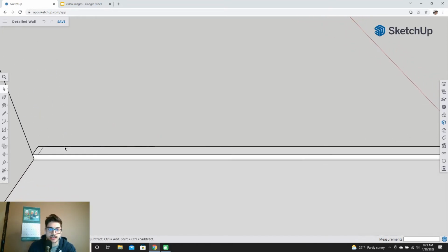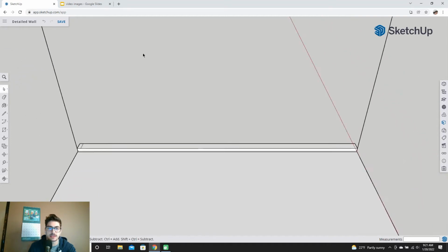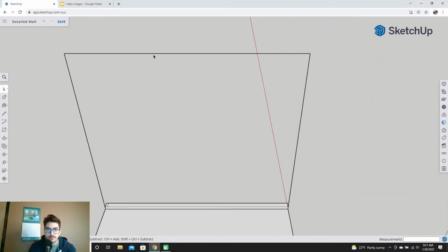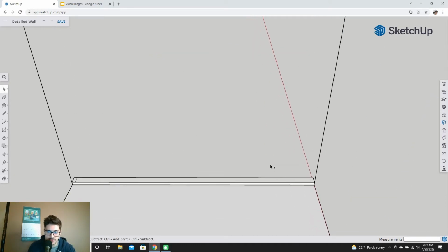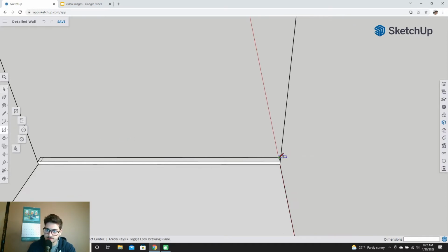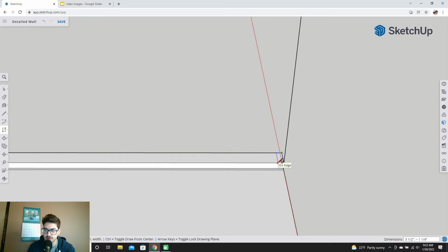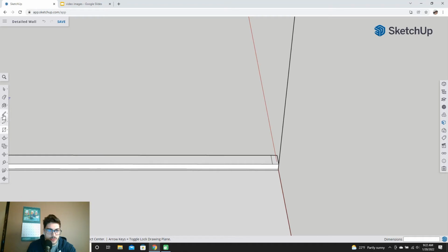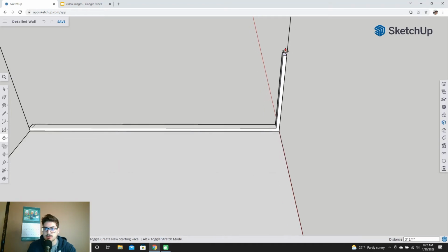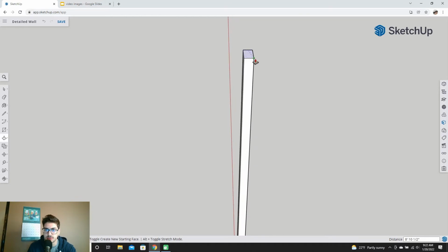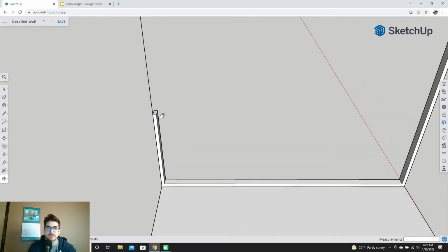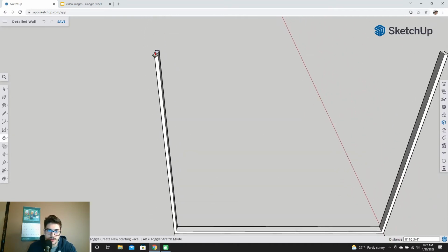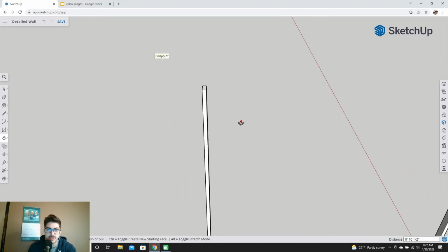Anytime you drop anything on a finished rectangle, so here we made this enclosure with the top, I'll get rid of that top so it doesn't happen every time I make a 2x4, because that's going to try to close off the space like we talked about. So then I'm going to just drop them on the sides for now, and this will also be 3.5 and 1.5. And let's get our outer two studs raised up. You should always have a stud on the extremities of your wall, on the far left and far right. It's pretty hard to finish drywall if they don't have a solid surface at the ends to anchor to.